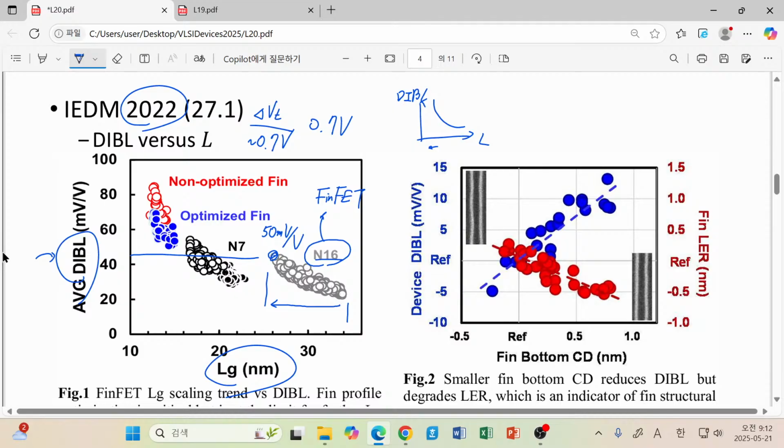For example, when they use an extremely small drain bias for the linear region. So that is the way to quantify DIBL. And when you have a look at this data, you can feel that maybe a good, acceptable value for DIBL is around 10 or several 10 millivolt per volt.